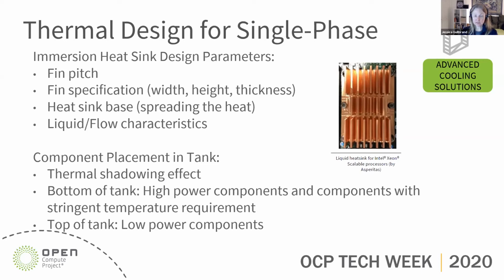In order to design an optimized heat sink, you really need to know what the liquid and the flow characteristics are, how those parameters change over time, and what temperature range you're operating in. You also look at the fin pitch and fin specification, so the width, height, and thickness of the fins, as well as the heat sink base: how thick, how good is it at spreading heat, what type of heat source are you dealing with, how much do you need to spread it, is it a more uniform heat source versus one that might have a lot of hot spots.